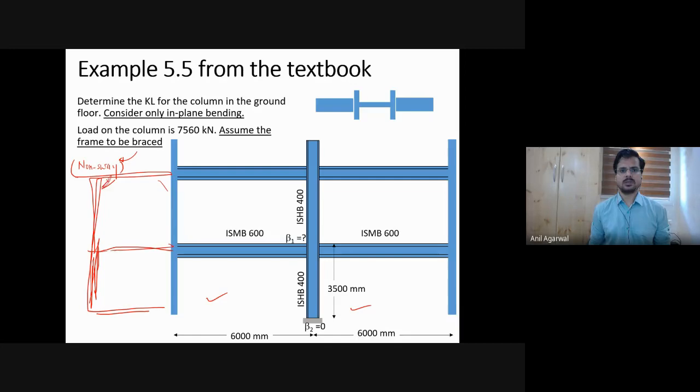Alternatively, you can make a very, very rigid, very stiff frame, like in case of a PEB, those kind of rigid joints that we had discussed before. So sometimes they provide very heavy joints and heavy beams. So these beams are much stronger than what is required for gravity loads. Gravity loads may be very small, but still they provide very heavy beams to create lateral restraint. Some similar kind of a system has to be provided to make it a non-sway frame. This may not be apparent from here, but it may be somewhere else through which it will be providing the non-sway characteristics to the entire frame.